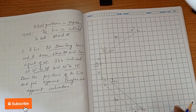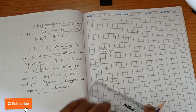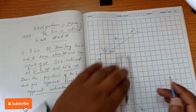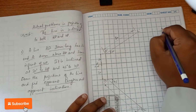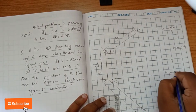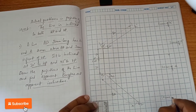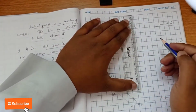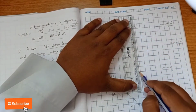So locus lines we have drawn. Now we have to find out the apparent lengths. How to find out the apparent lengths: from this end, we have to draw a straight line till this. I'm going to mark this as the locus of A dash, and this is the locus of B1 dash, and this is the locus of A, and this is the locus of B2. From B1 dash we have to draw a straight line till the locus of A.